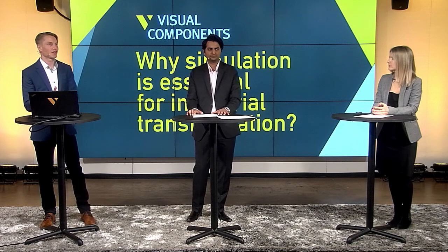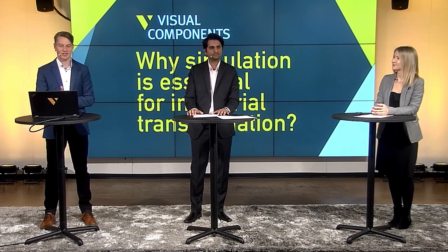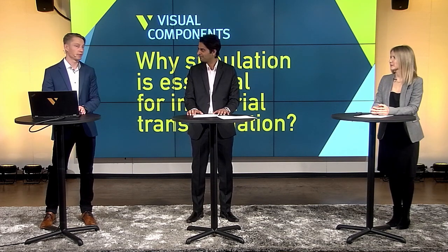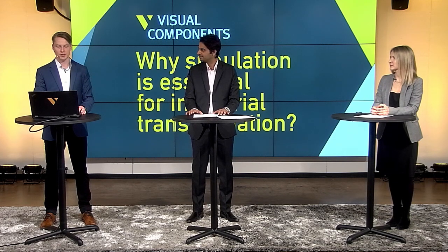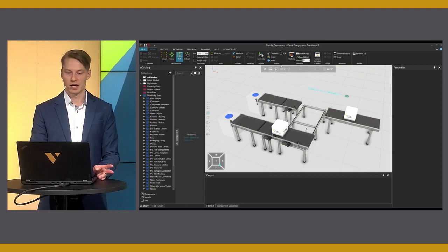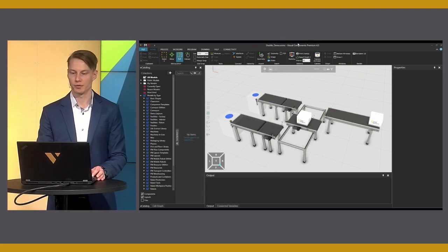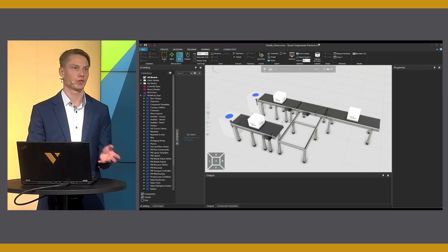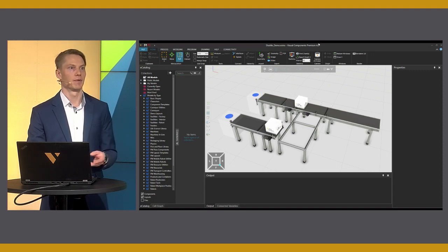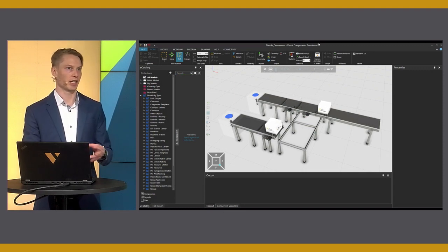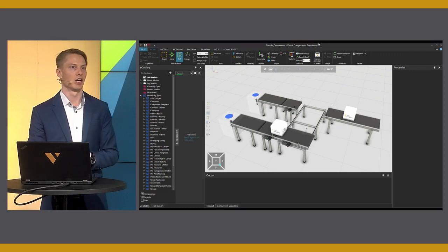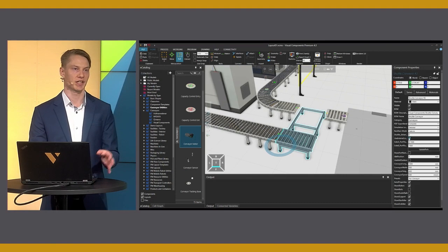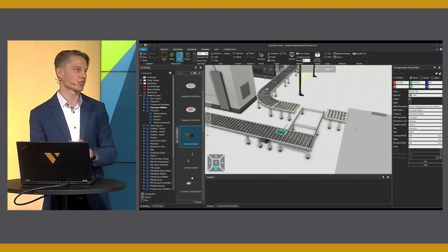I believe, Yana, you are referring to virtual commissioning, and that's a very interesting and hot topic. We have connectivity capabilities with numerous protocols. Once again, let's take the shuttle conveyor from the layout we used as an example. If we wanted to validate our PLC logic with that, we could start by isolating the problem and setting up a simple test scenario in a separate layout and connecting it to a PLC via OPC UA, for example. After validating, we can easily load that same setup into the main layout and replace the shuttle there.